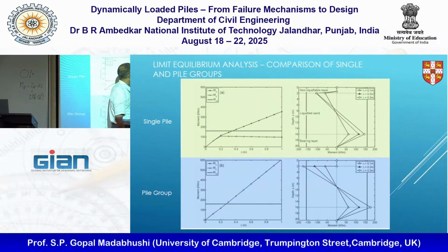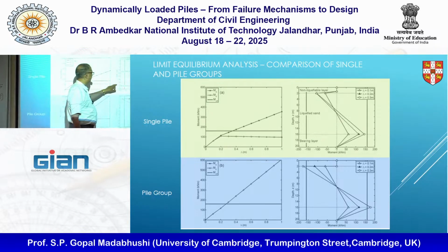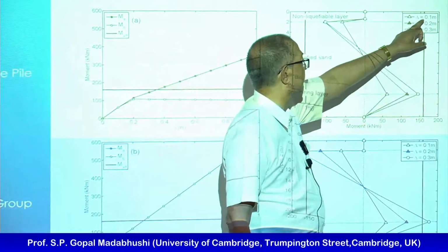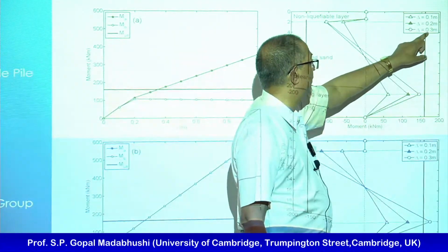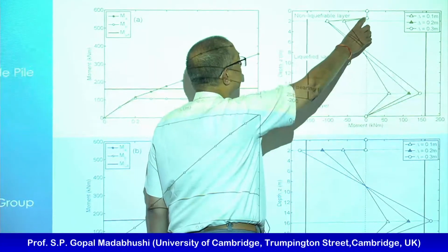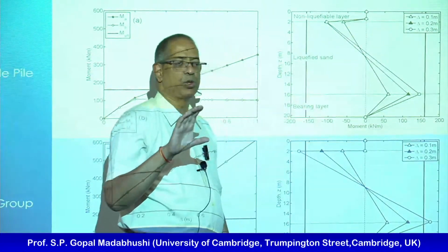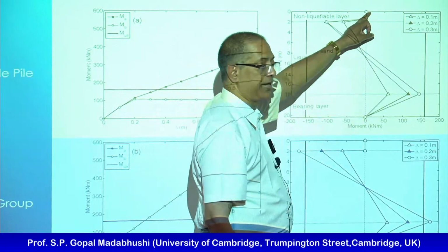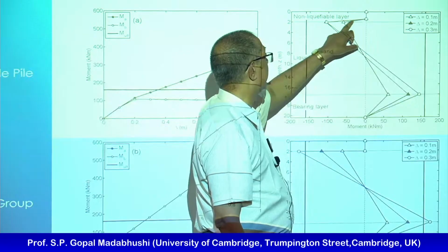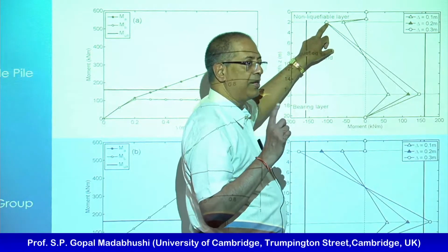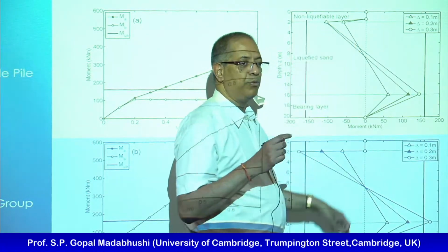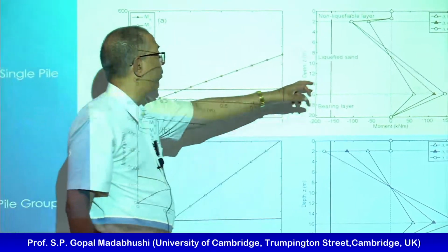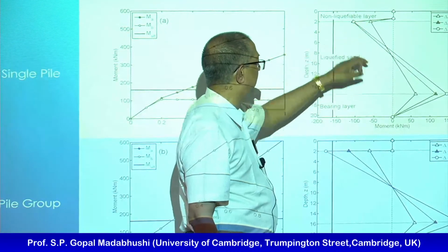So if I were to look at the bending moment distribution for different amounts of deflection, 0.1, 0.2, 0.3, you can plot this. Because the pile cap is so rigid, there's no change, so that's pretty much zero bending moment there. But the pile will have some moment, which is my MA being applied. And that obviously is increasing with deflections.